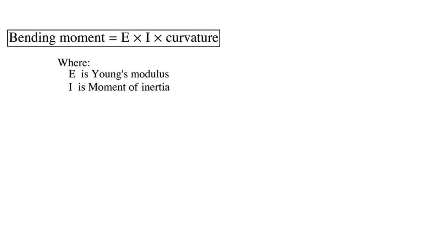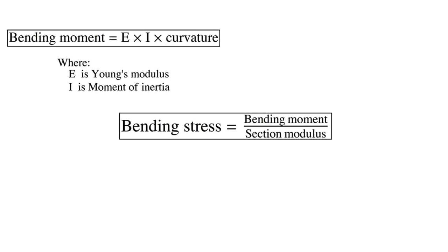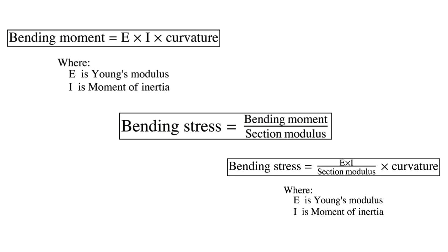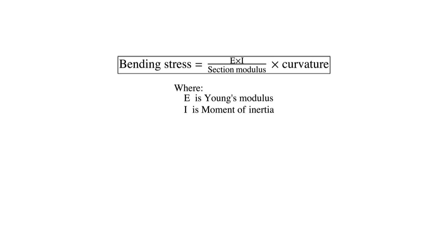In beams and columns, bending moments are linearly related to the curvature, and bending stresses, which is the main thing in designing beams, are linearly related to the bending moments. This means that visually, seeing curvature is seeing relative bending stresses. Yes, curvature is how we actually see relative bending stresses. So it's worth it to have more refinement in recognizing curvatures and their relative amplitudes across the beam or column.